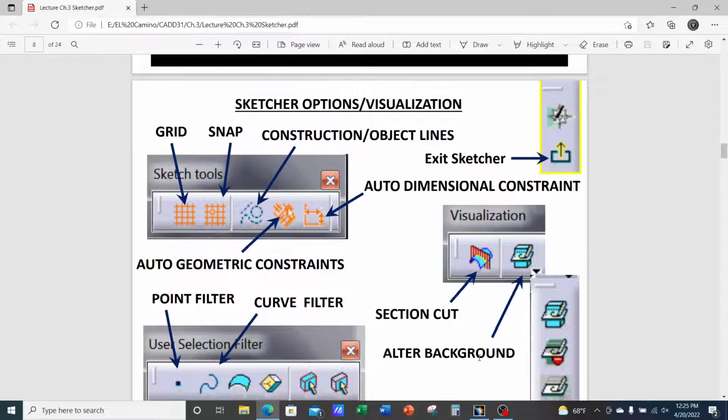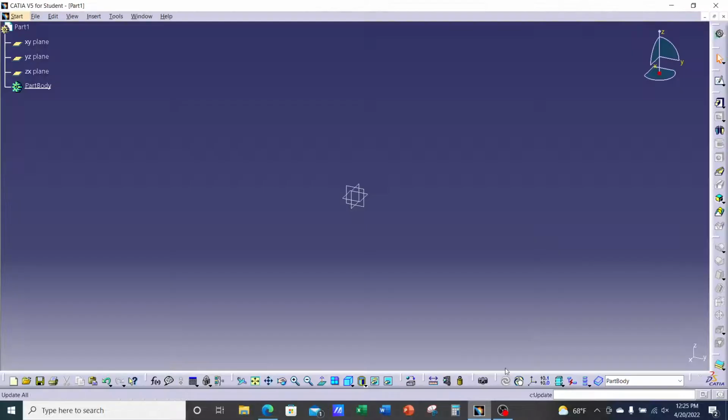All right, so let's go back to CATIA. When I create a sketch, it's going to automatically start populating the tree. Notice I clicked on sketch, it's orange, it's active. And if you don't know what to do next, just read here on the bottom left corner. It'll tell you what to do. It's asking you to select a plane or a planar surface on a solid. I'm going to pick the YZ plane. It's this vertical plane, as you can see.